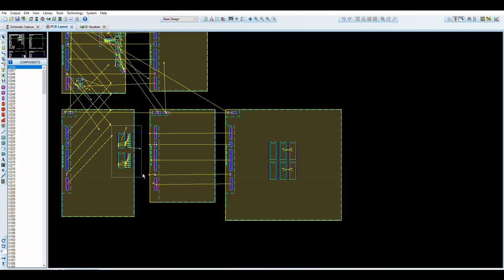Similarly for the Sprite board, I wanted to make sure that my Sprite scanline logic, and we'll get onto the Sprite board and how it works in more detail, with its pull-up resistors, because it stores inverted pixel values to aid in having a nice quick pixel test, was placed consistently. Then I could let the auto placer more easily place all of the other components around, and also it would be nice and neat for later soldering purposes.